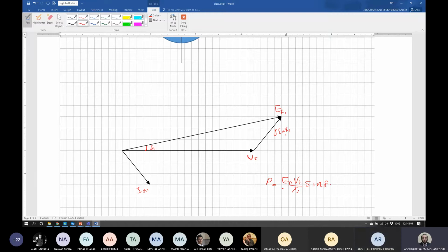For the synchronization conditions we discussed, terminal voltage has to be the same as the grid. So if you would like to increase the power and you increase the voltage, it will disconnect it from the infinite bus. You cannot increase the voltage. Volt has to be the same as the infinite bus voltage. So you cannot increase or decrease V terminal.